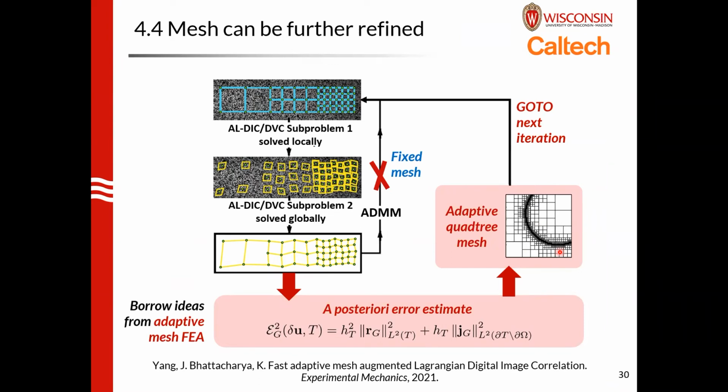For the second comment, the images can be large, so maybe you have heard of the cumulative mode for the tracking and also the incremental mode. For the cumulative mode, you are always comparing with the very beginning reference image. For the incremental mode, you are always comparing two subsequent frames and then eventually doing some interpolation. If your deformation strain is usually less than 30%, which is just an empirical number, the cumulative mode works well.